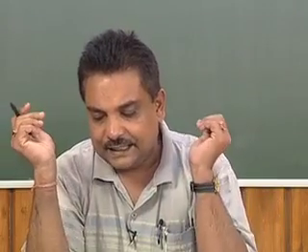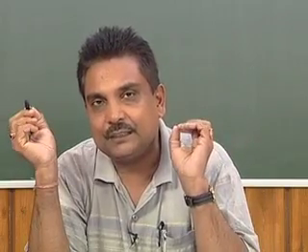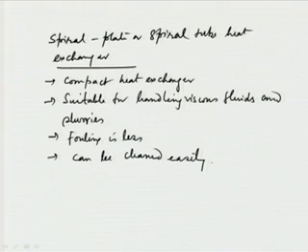Okay. So, the one fluid is just adjacent to the others, and it continues in the form of a coil, like a centrifuge. So, it's like a coil, and this continues. This maintenance may be easy, some cleaning may be easy, but the difficulty is in the fabrication of a spiral plate or spiral tube heat exchanger in comparison to a cylinder tube heat exchanger or even a plate and frame heat exchanger. But a spiral tube or spiral plate heat exchanger would be a much more compact heat exchanger, we should say.